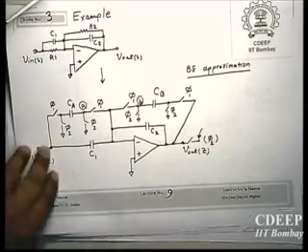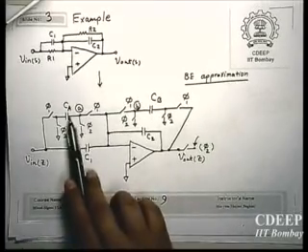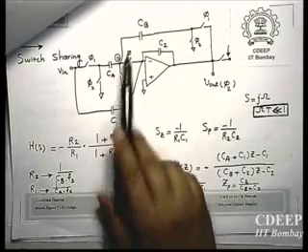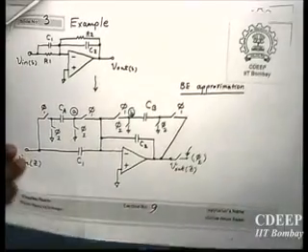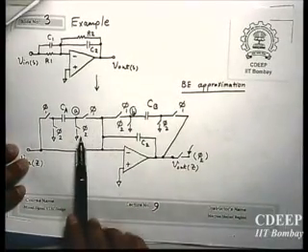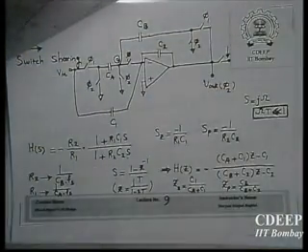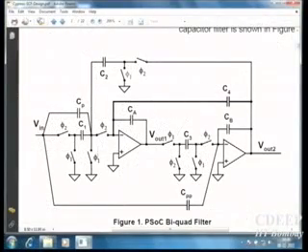Now if we connect B to A, so left plate of CB will come over here to node A. So left plate now is connected to node A. And then you have phi 1, phi 2, these two are removed and the remaining part will remain as it is. So same thing has happened here. So left plate is connected to left side of the switching network.